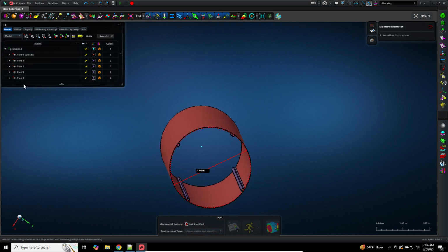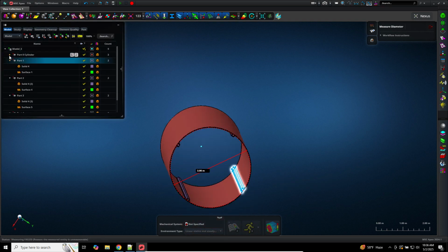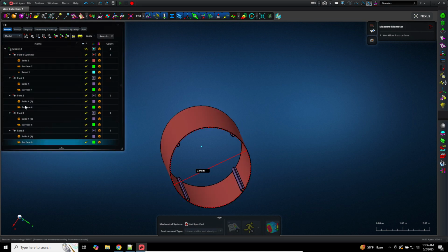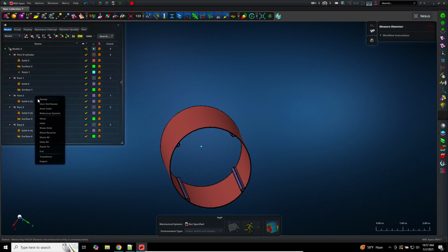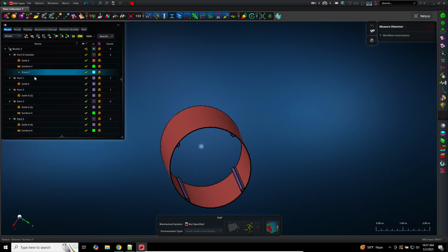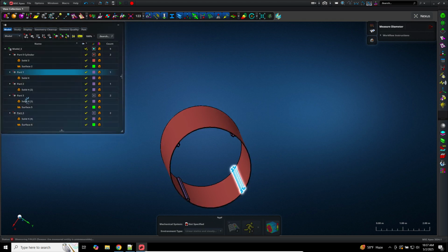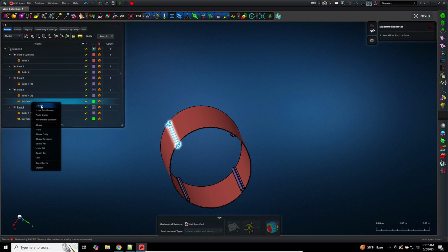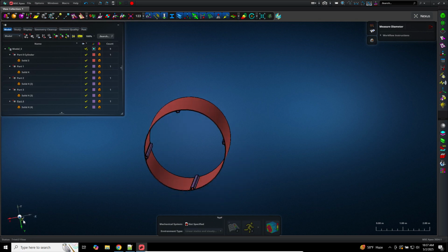Okay then. Now, when you import your geometry, you need what are called surfaces. Here, this example already has surfaces, so let me go ahead and delete all those. Now, I'm assuming that you only have solid geometry. So this is what that solid geometry looks like.